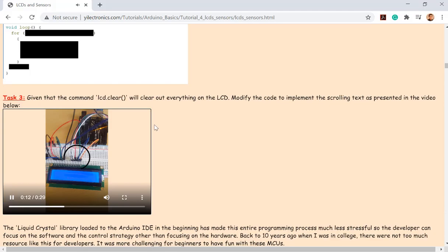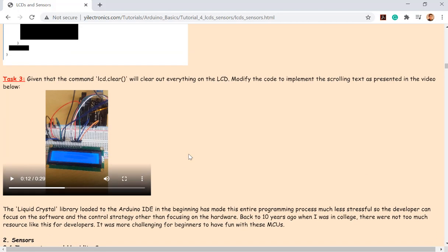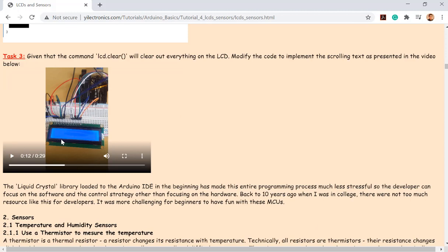It's pretty simple. The way to clear out everything on the LCD display is this function, LCD.clear, parentheses. Because it's a digital system, it is able to display any digital pattern on the monitor really quickly. What this does is you write that string, Durango, to the monitor at one position, and you let your microcontroller keep changing the variable, which is the location, in every loop.